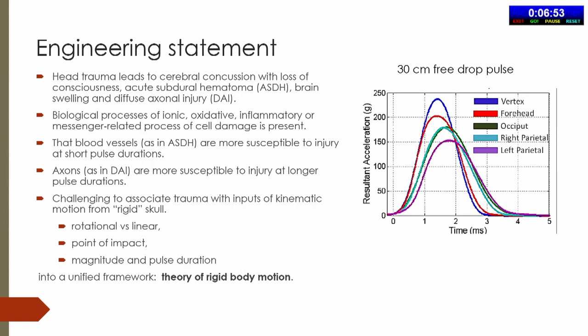When we look at the engineering statement of that, it is based on a lot of 30 centimeter free drop pulses, and we measure the accelerations at the vertex, forehead, occiput, and right parietal, and then measure against time. These are short time durations, milliseconds. So you look at the impact itself.